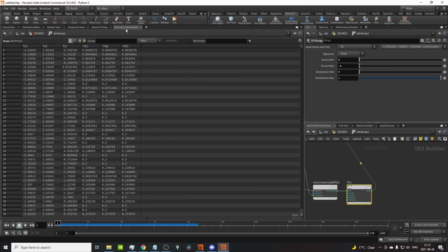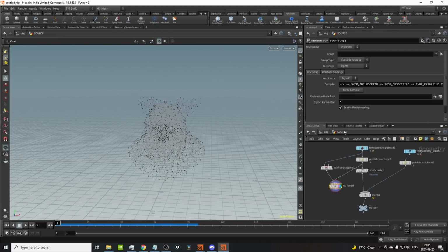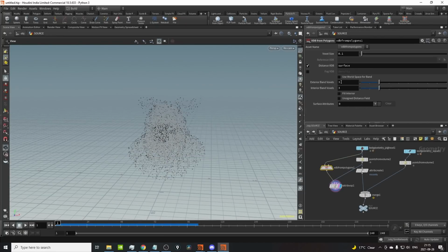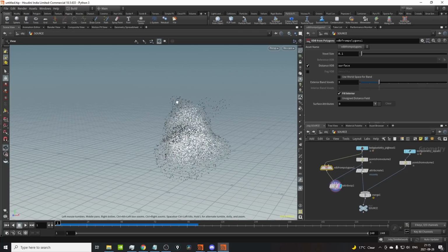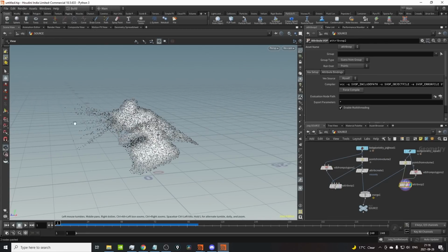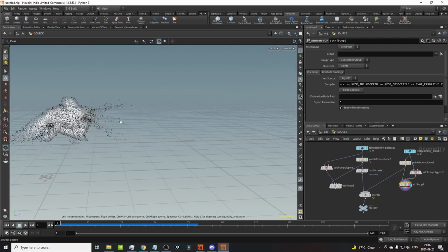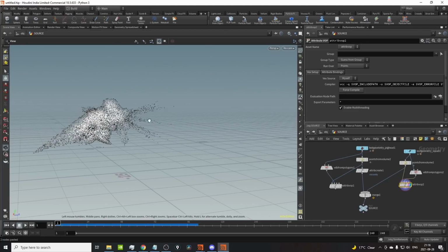Now, you can see that actually our output max is 0.3. That's an SDF thing. It has to do with how many interior bounding voxels you have. If we just hit fill interior, you're good to go there. So now this gives us really what are the particles on the edges and what are the particles deep inside. And if we do the same thing for our good old Squab, we will see that his tentacles and his claws and everything is a lot darker than the inside.